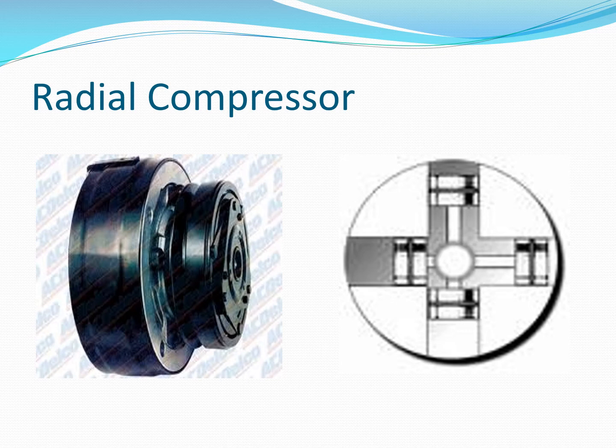The problem with these compressors was there was a very fine O-ring in the front and the back of the compressor where the black ring was sealed to the inner housing, and it leaked refrigerant. These were very prone to leakage, and even though they had some problems, GM used it pretty much the whole decade of the 80s. So you will be seeing these.